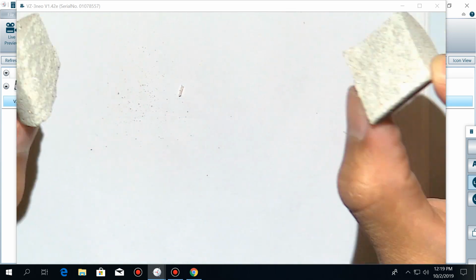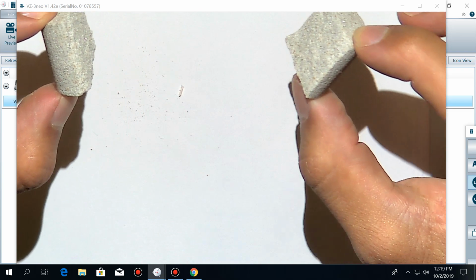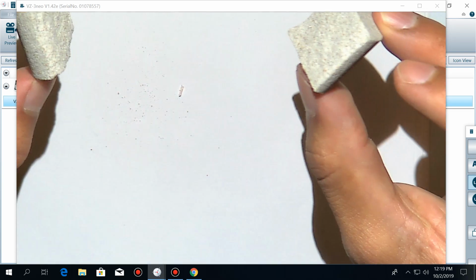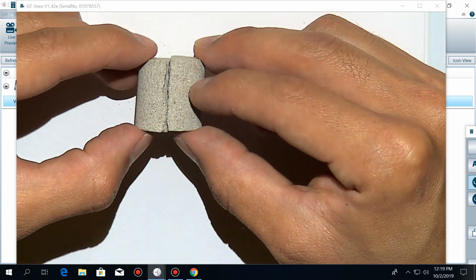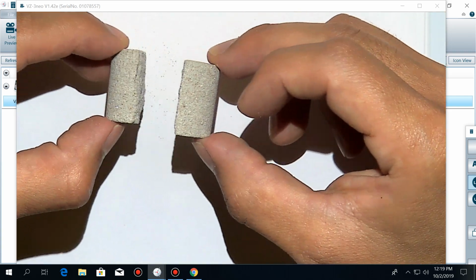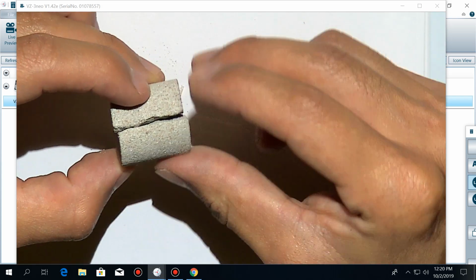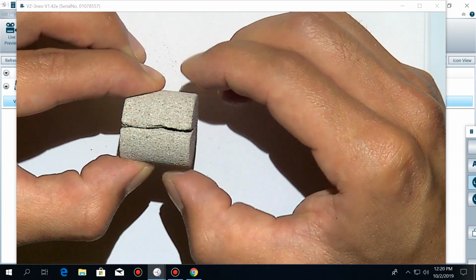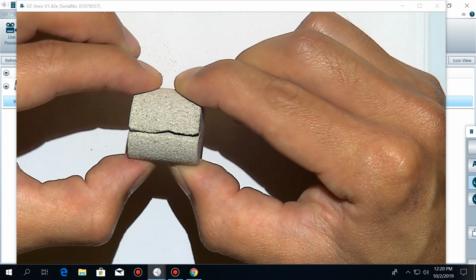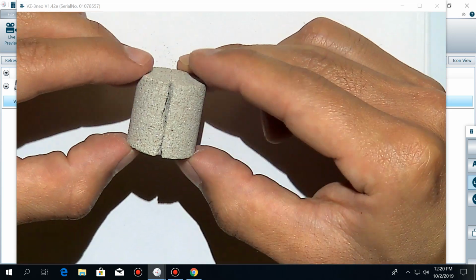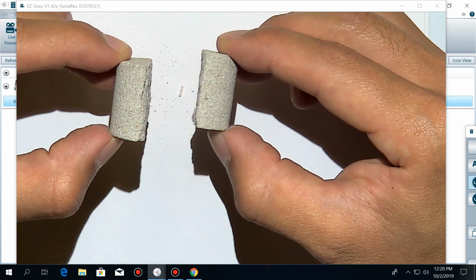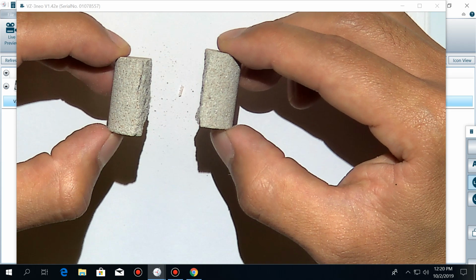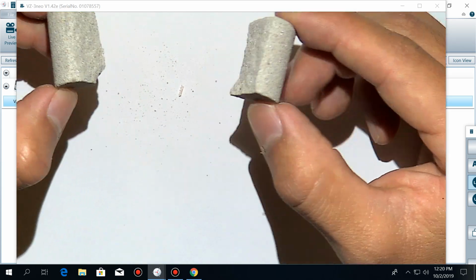It seems like a silly example, but it's not. My point here is that tensile strength, especially, is a property that depends on direction. For example, if I try to now pull this with my hands, I'm not going to break it. It's too strong. But in this direction, I can break it. Similar to elastic properties, failure properties also can be anisotropic and depend on direction.